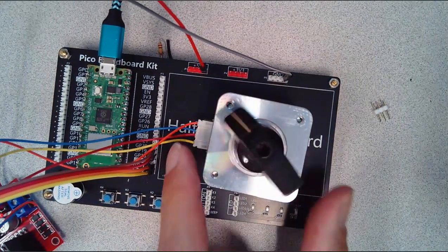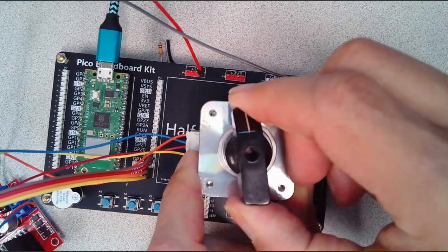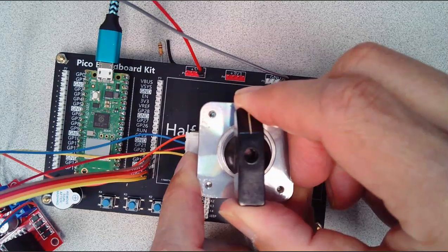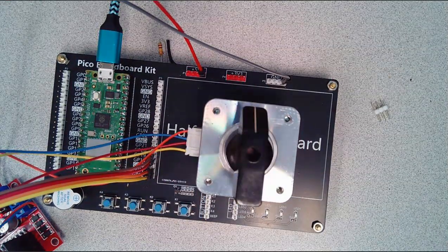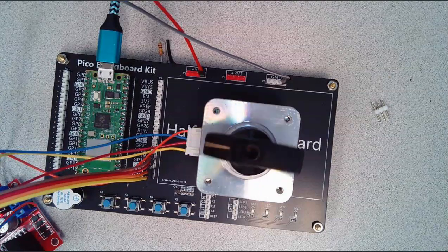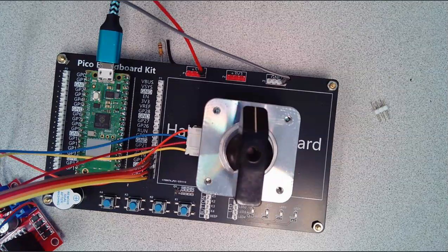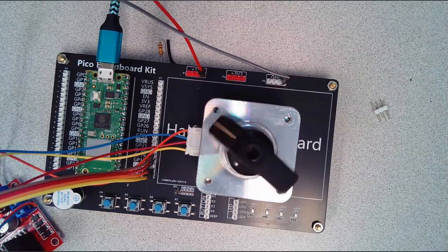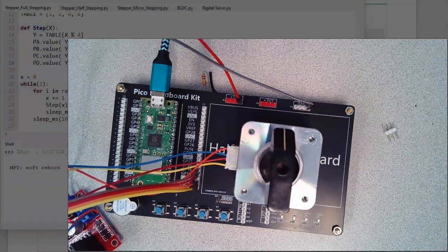For stepper motors, they don't really know a home position. I can sit there and twist it. I'm stalling the motor. Now I'm calling that the 0 position. It goes 200 steps. That's 1 rotation. And you can see the coils here. The ones side by side are 1 coil. So orange and blue are one coil, red and yellow are one coil. That is full stepping.